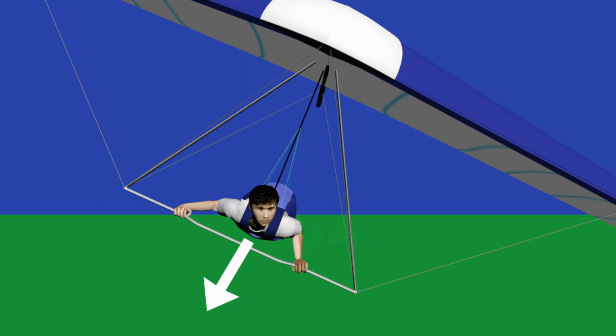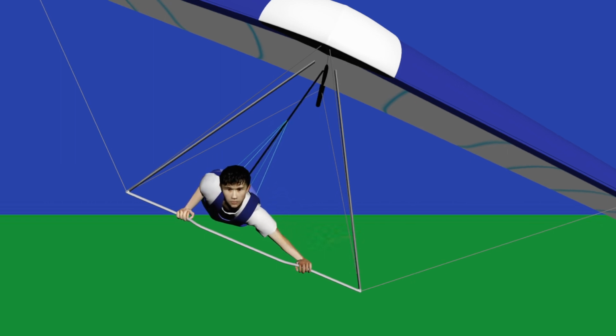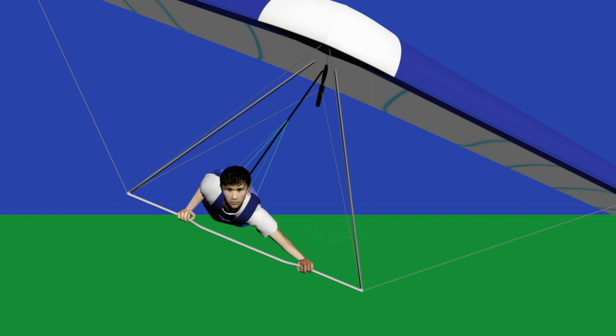To go back to straight flight, the pilot needs to shift his weight to the right. For this movement, he will need to give a little more input, overcome a little more resistance than with the initial turn to the left, since he has to overcome more gravitational pull. After all, he has to push himself more up than with the initial turn to the left.